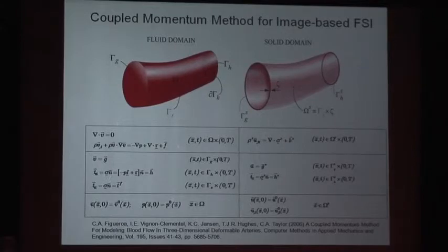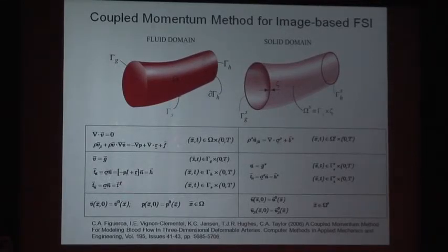And the idea behind it was basically taking a lateral traction force and imposing a fictitious body force in the elastodynamics equation, and then relating it, provided that you have a thin wall assumption and a linearized approach, you can relate the traction to the body force and essentially embed the elastodynamics equations into the fluid mechanics equations at a variational level.